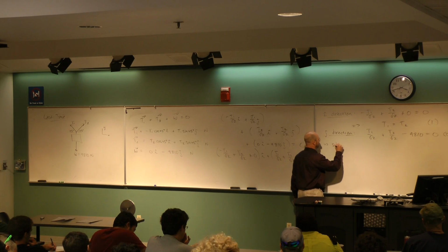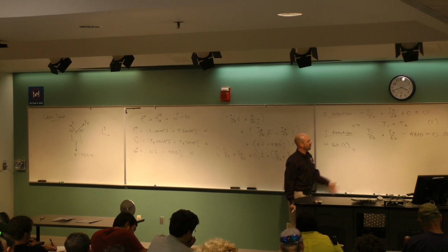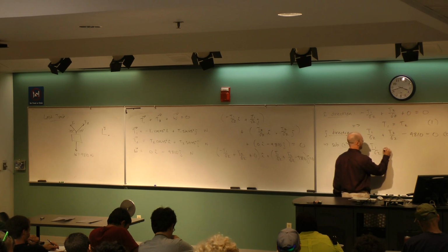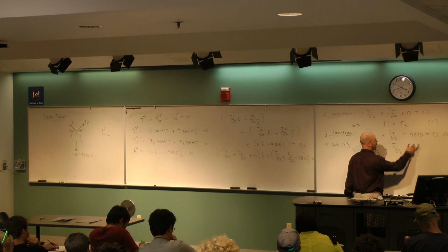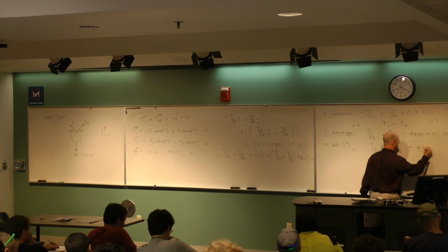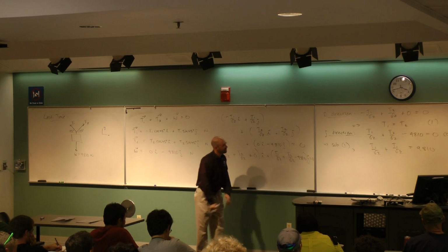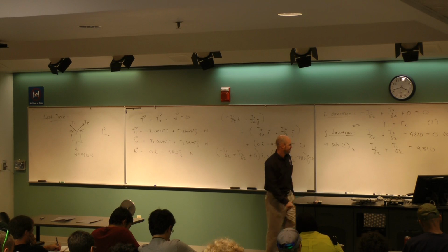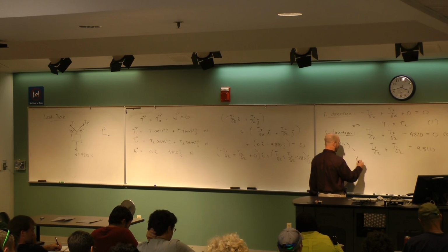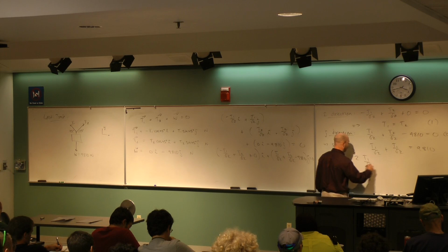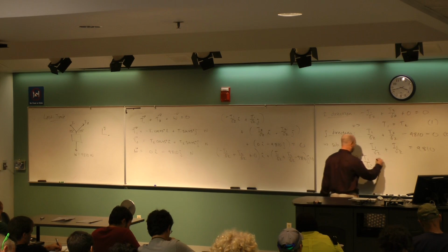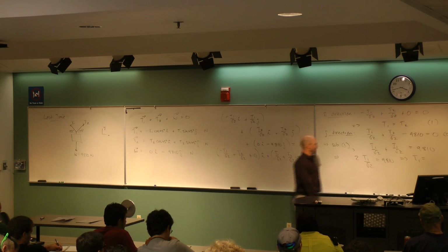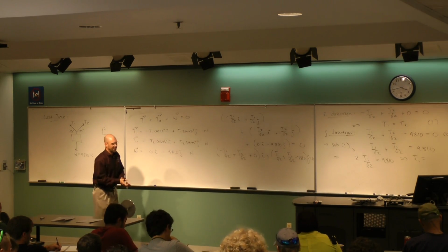I can sub equation 1 into equation 2 and see what I get. Where I see a T2, I'm going to put a T1. So I'll get T1 over root 2 plus another T1 over root 2. Can I move the 9810 to the other side like that? At this point, can I combine these terms? This is going to be 2 times T1 divided by root 2, and that equals 9810. Somebody bang that out for me. T1 would be what? Root 2 over 2 times 9810.